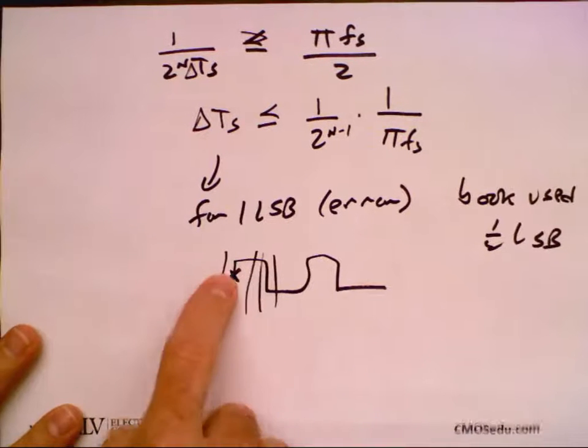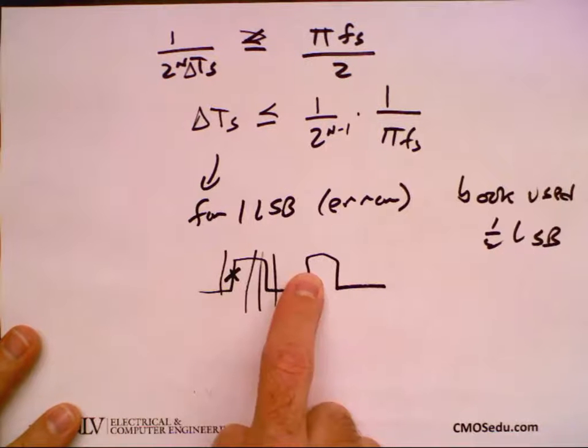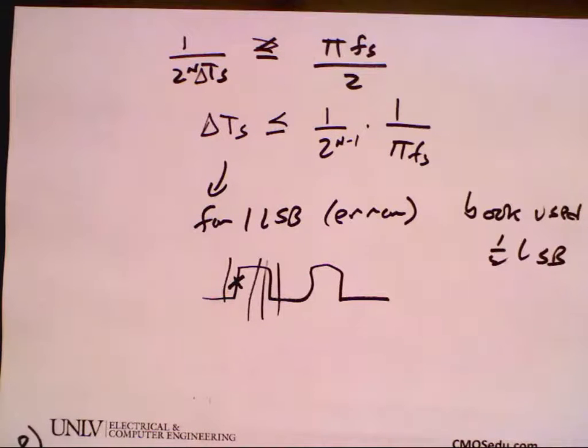Yep, then you could trigger here. Yep, and then look over here as well. And then what would you do? You could put the scope on a histogram and get a distribution for the jitter. You could get a nice little probability distribution. This is a very practical, very big deal.